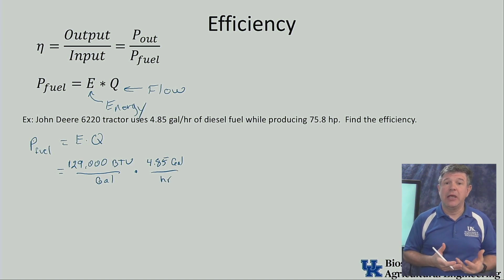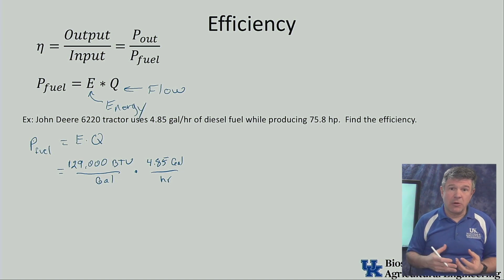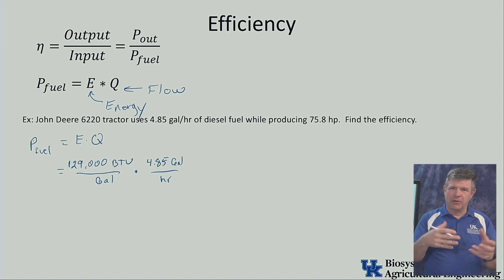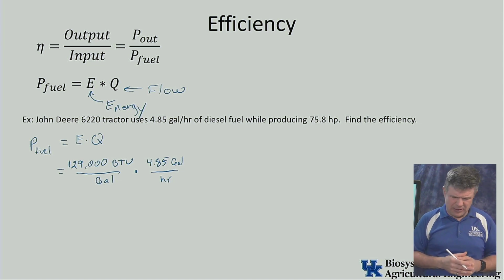That's all I need to put into that equation, except that now I have to look at the units and get the units to come out the way I want them to be. So what units do I want? I want horsepower. Horsepower, oh yeah, I got to go to that foot-pounds per second kind of a thing and get there. So what do I have in terms of units? Well, I can look right away here, and hey, my gallons will cancel off. So I can cancel off those two gallons, and I have BTUs per hour.